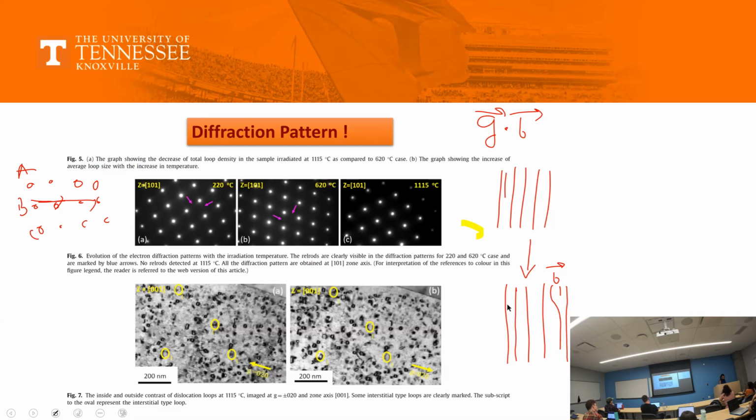When that stacking fault is already there, because one of these layers has drifted a little bit, and you also have a dislocation loop on it, so there is already a plane where there's a fault, plus there is an extra added plane, those kinds of loops are known as imperfect loops. This is an imperfect loop example.